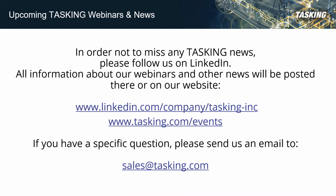All right, there's another question. Are your additional tools, safety and performance related, compatible only with applications based on AUTOSAR and MCAL? So let me take this up. Basically, these tools work with classical C programming, so embedded C programming. AUTOSAR and MCAL is also one application of this. So to answer your question, in case you have classical software which is not AUTOSAR, then you can still use the safety checker, the embedded profiler and the multi-core performance tool. Thank you.